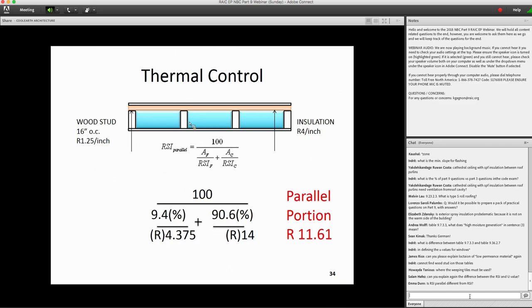You can have the air barrier on the sheeting, and instead of using a regular Tyvek, you might want to use a peel and stick membrane that you guarantee will maintain the air tightness. But in this case, the air control layer will be on the cold side, so you do need to use another component as a vapor barrier that has to be on the warm side. So in some cases you can use it, and in some cases you need to have it separately.